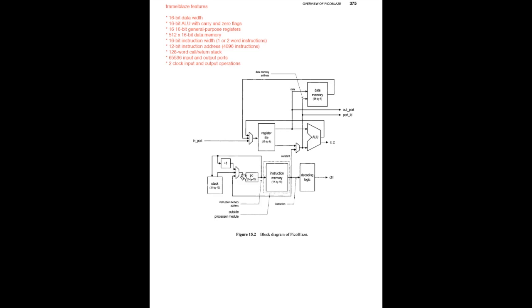So the redesign has a 16-bit data width, a 16-bit ALU, carry and zero flags, and sixteen 16-bit internal registers, R0 through RF. We now have a 512 by 16 data memory, called the scratchpad memory, inside of the processor.